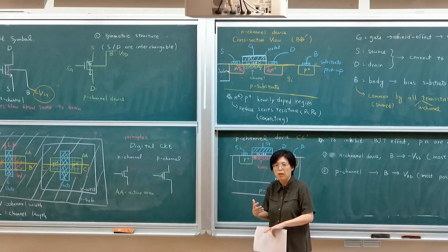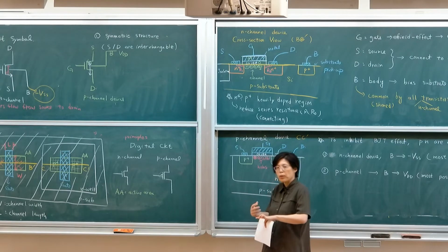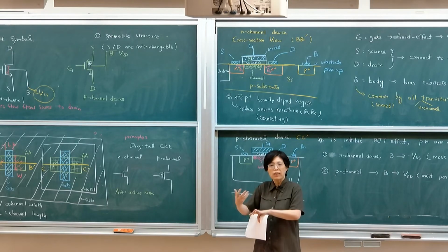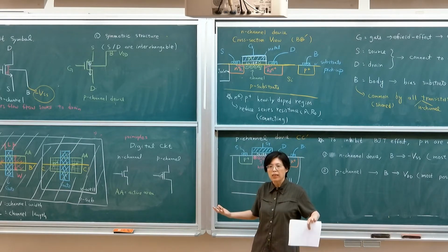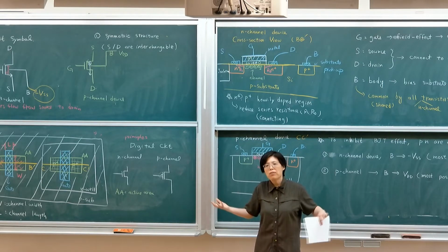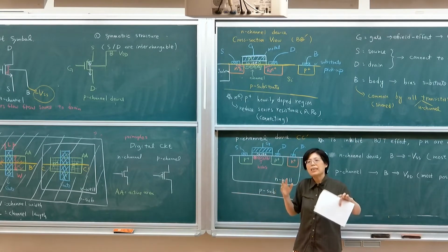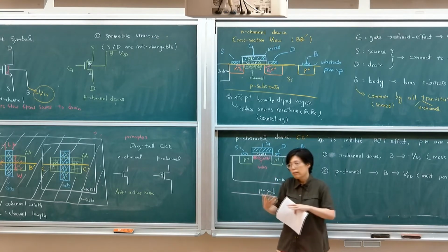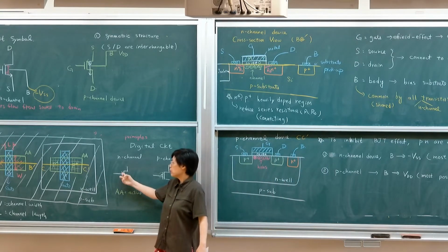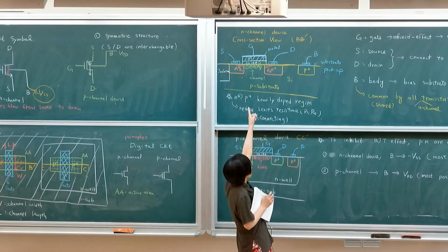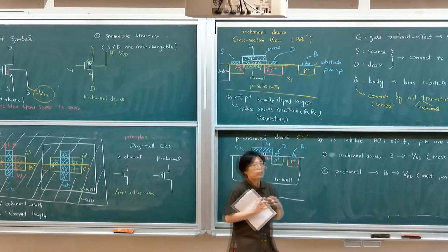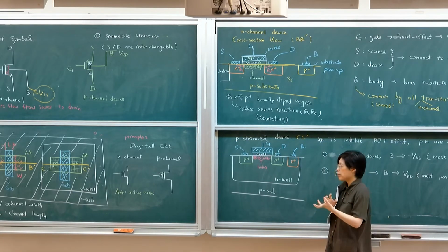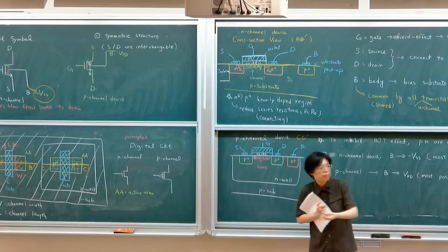And that is why it has become very powerful in delivering what we call CMOS technology. If you consider current gain, it will have infinite current gain because there's no gate current. It's not essentially infinite if you're operating in AC mode, but in terms of DC, there's essentially no current flow because of the oxide insulation in the MOS structure. So it's very powerful in delivering low power complementary operation. That is why it has become very popular.